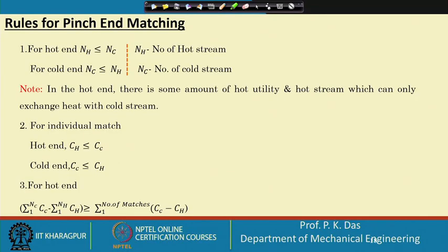Welcome back. So, we were learning heat exchanger network analysis by the pinch technique. The pinch point I have introduced divides the problem into two parts: one is the hot end problem of the heat exchanger network, and the other is the cold end problem. Each of these ends can be designed separately, and the design has to be started from the pinch point. These were the messages I gave in the last lecture. Now, let us look at the slide.